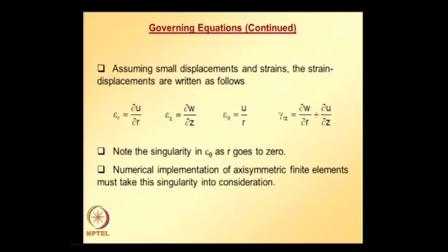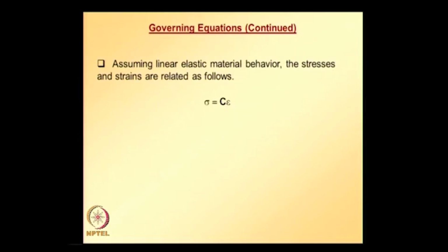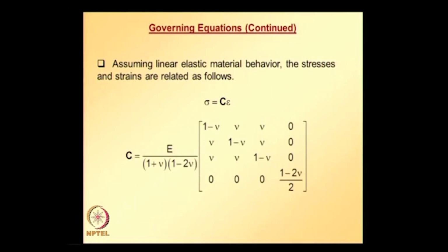Similar to what we did for plane stress, plane strain problems, assuming linear elastic material behavior, stresses and strains can be related via this equation: sigma is equal to the constitutive matrix, denoted with capital C, times epsilon, where the constitutive matrix is defined like this, which depends on 2 material constants, Young's modulus and Poisson's ratio.